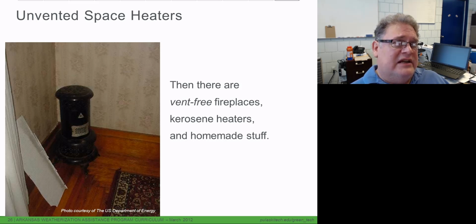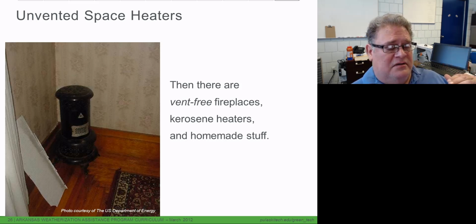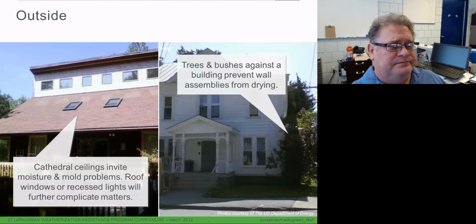The other thing is, if they get dirty at all, they stop burning efficiently, and your efficiency goes down. That means that your potential for carbon monoxide goes up. We'll see all kinds of things. And as far as putting water in the air, kerosene is about the worst. It has the most water in it for liquid or gas fueled space heaters.